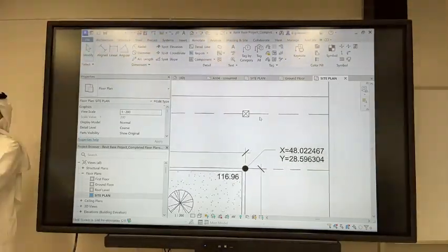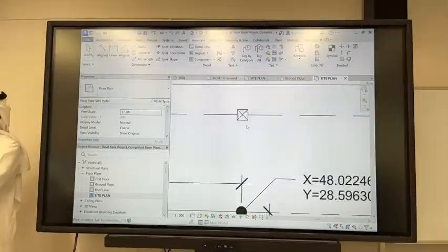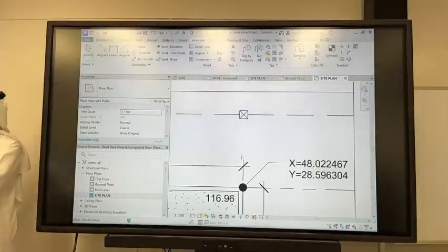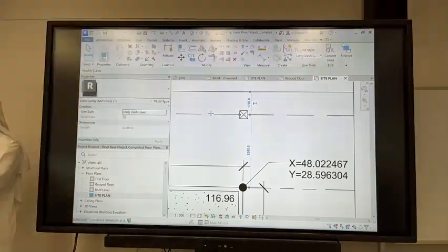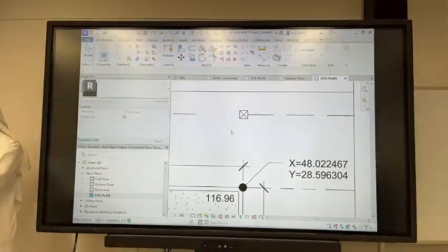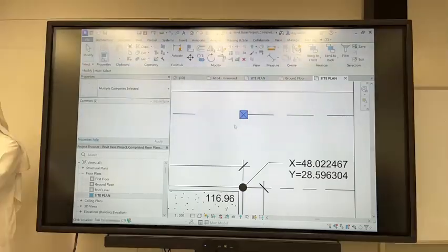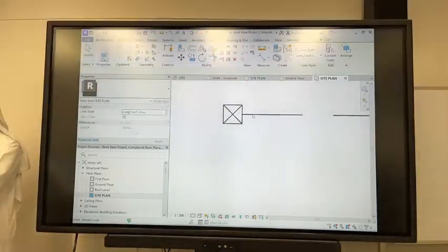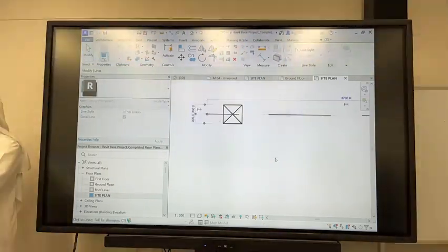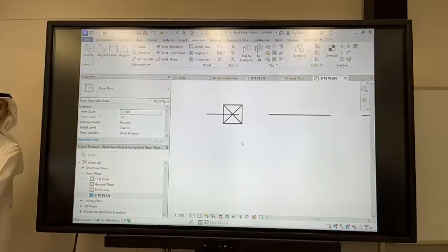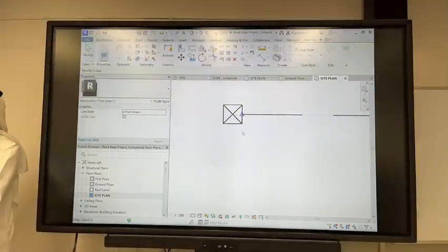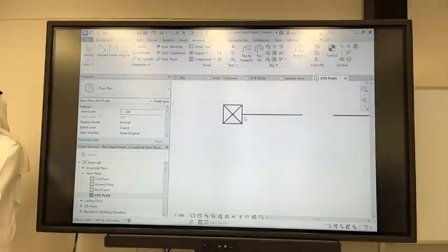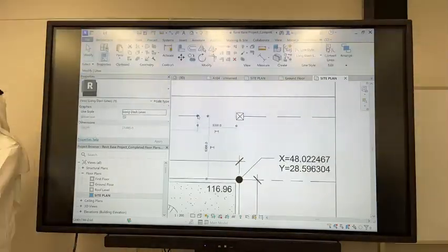Okay? Sometimes with dashed lines, let's say this has to be here, okay? But your dashed line might be coming in a weird place in your handhold. So sometimes what you can do is you cut the line to come to a point, so you can see the dash clearly before and after the box.